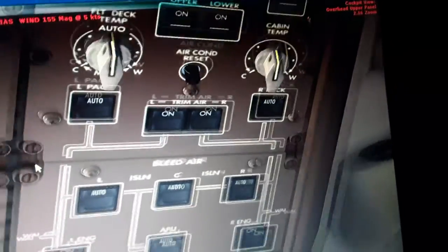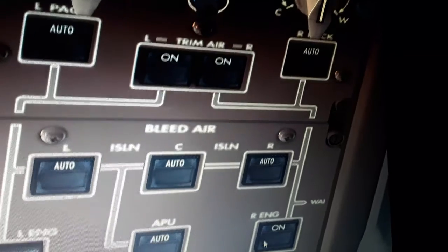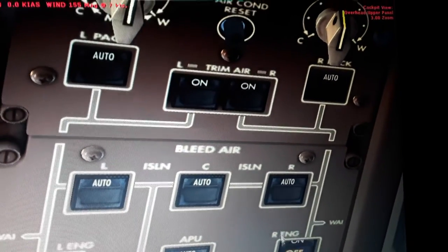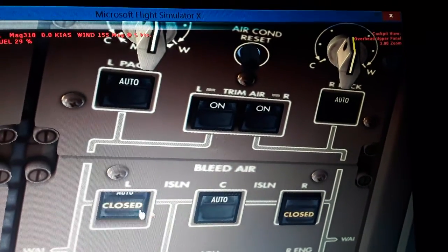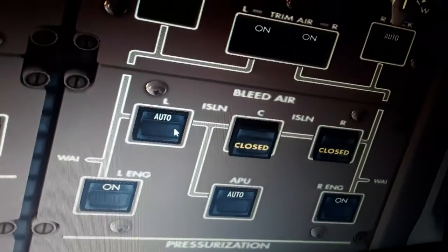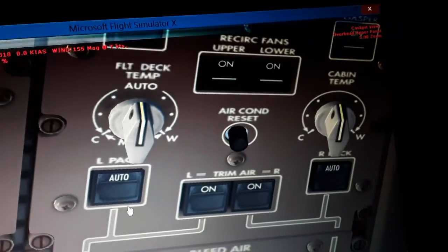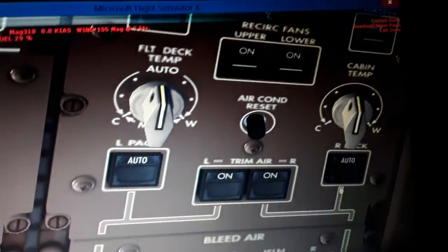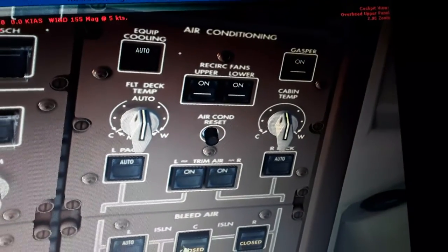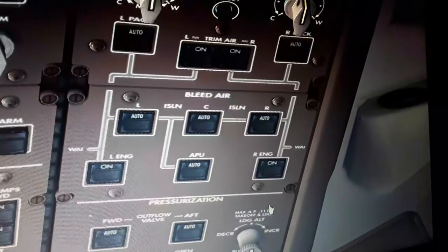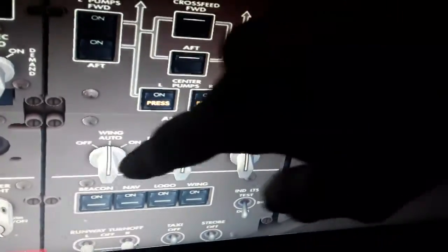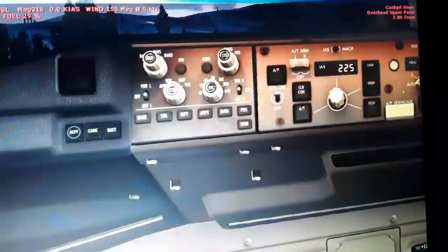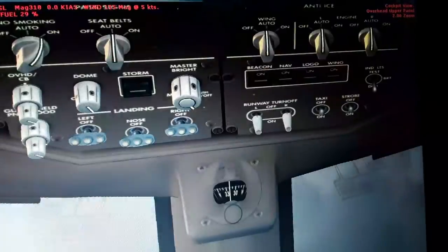So we have here also the air system, the left and the right engine. This is the left, right engine. This is the APU compressed air. This is isolation valves. We use this to isolate an engine bleed. I'm going to talk to you about it later. This is the PAX bleed that supplies compressed air from the engines and the APU. The cabin pressurization system, the wing and engine anti-ice here. You see the other needs to pressurize hot air for this. And also the hydraulic fluid tank.